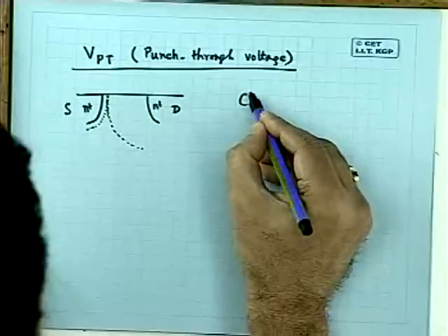So what people do is use a slightly higher substrate concentration and also a dual channel implant. They do 2 implants. One is a shallow implant at a low energy and a low dose for the control of the threshold voltage. It is followed or preceded by a deeper, slightly higher dose implant. That means channel implantation is done in 2 stages.